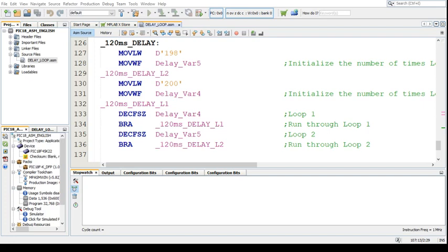And there's another way to do delay loops without using the formulas. You could literally just guess the two values, use your stopwatch, and increase or reduce accordingly. The problem with that is it takes time, and in certain situations you don't want to spend too much time on delay loops, if you know what I'm saying.